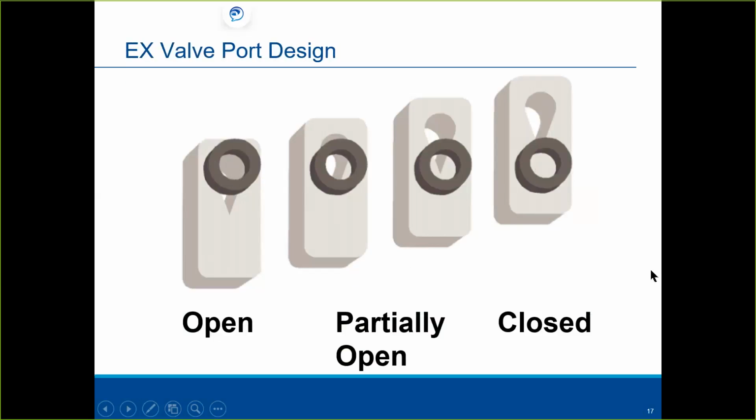All right. And things like our newer refrigerants, especially like CO2, for example, and I know I keep going back to that because I teach a lot of it now. CO2, you're going to see a lot more in your supermarkets, obviously, because of the EPA ruling that's coming out. It's very hyperactive, so you need everything electronic. Everything's got to be modulating. It's a whole different animal.